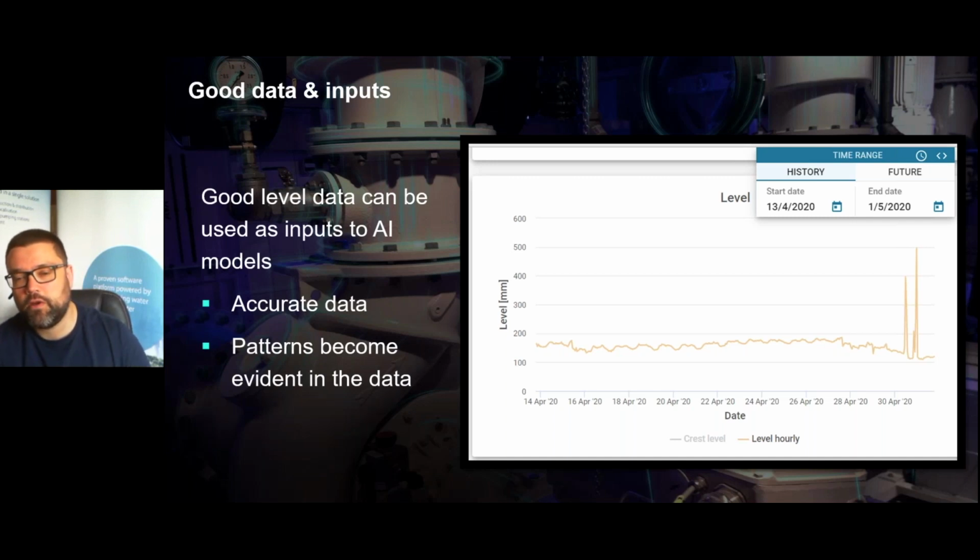So in the period from the 14th of April up until the 28th of April, you can see a fairly clear diurnal pattern, and that's what you would expect in dry weather flow conditions. Now the pattern itself is a little bit flat. That reflects that people in the UK are not leaving their homes at the moment. We're in lockdown. But you can quite clearly see that evening, morning, nighttime change that you would expect with dry weather flow.